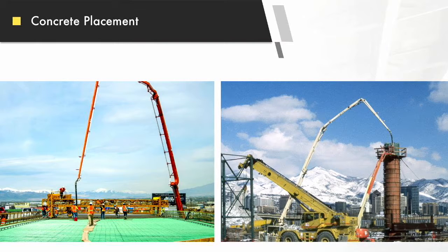Pumping concrete. Our specification says test the concrete at point of placement, right? And I know a lot of inspectors say, oh, it's a pain in the ass to get out on the deck and test right there on the deck. There's no reason, like this picture, the contractor has no problem putting out some plywood out there so you can run your wheelbarrow out there. It's just real critical to do your tests at the end of the pump.